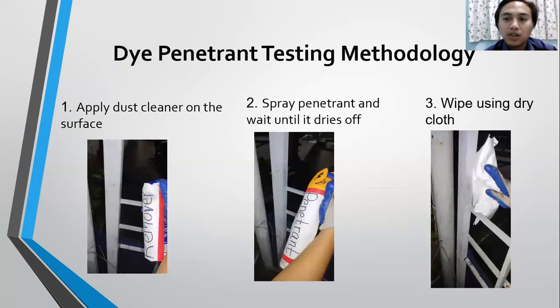For the third one, after we apply the penetrant, all the penetrant on the specimen should be removed with clean, dry, lint-free rags until truly clean. The part or material should be rubbed vigorously until the penetrant is not visible on the dry rags. Next, remover should be sprayed on another clean, dry, lint-free rag and used to vigorously rub the part again until there is no penetrant visible on the rag.